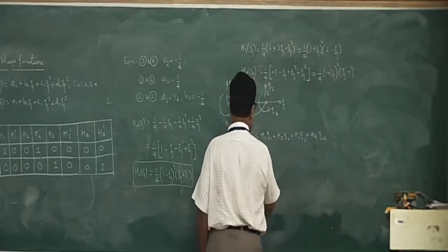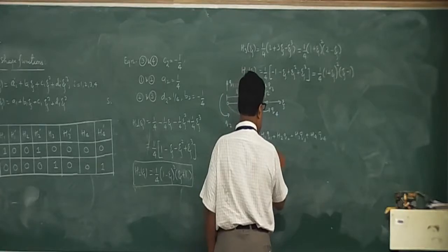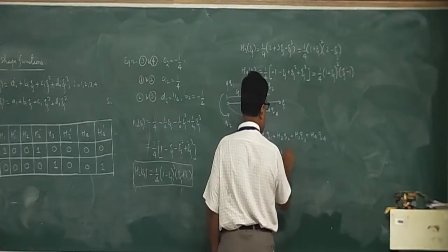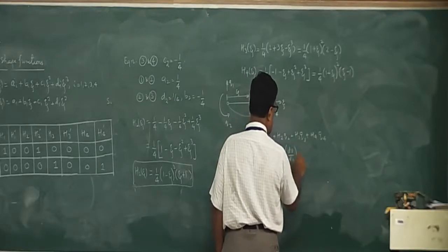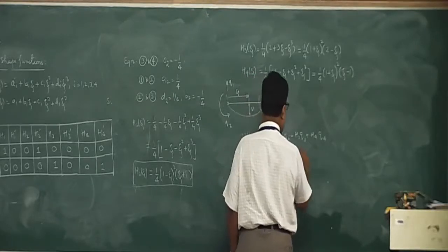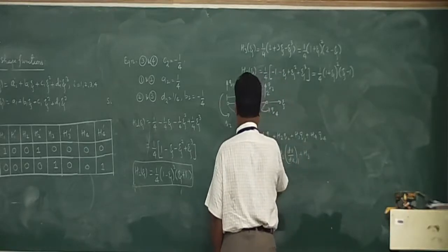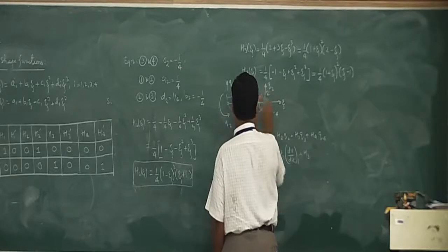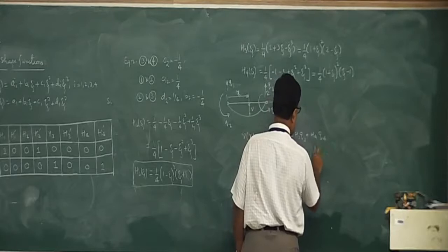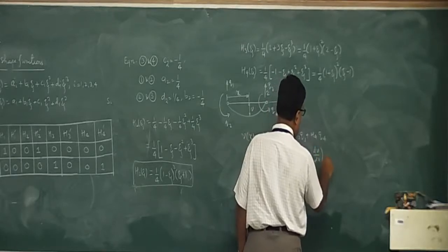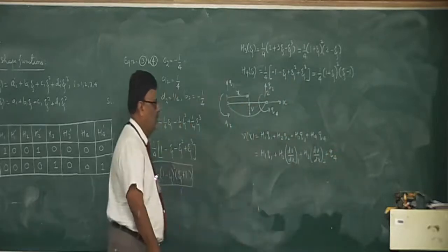This can also be written as H1 Q1, and H2 is there, obviously, where Q2 is nothing but dV by dx at 1, and H3, Q3. Of course, this is not the deflection at x, please remember, it is at a given value of x. Q4 is dV by dx at 2. So these are the values which are to be found out.